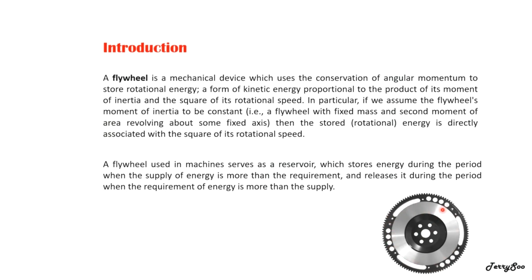When there is excess, the flywheel will rotate at higher speed. So the angular kinetic energy will be stored in the flywheel as it rotates faster. It will release the energy when there is a need of energy during other strokes. Then the flywheel will rotate slower and slower by stages according to the engine requirements.